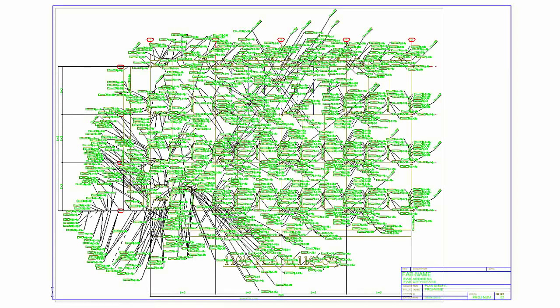Now, I've had a lot of users forget to set up their filters on their erection drawings or their general arrangement drawings in order to either hide all of the model marks or to set up object level settings so that there's no part marks shown and they show up nice and cleanly on the drawing. If you forget to do this before you make the drawing, it will take forever to create because Tekla's going through the algorithm of trying to offset all those part marks and then drawing and rendering all those objects. So it kills the drawing creation process, and the opening process is extremely slow.